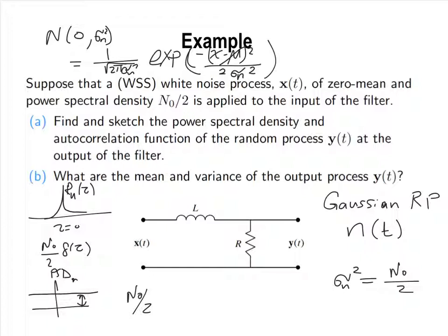Okay? So that at any point in time when you are trying to solve a problem or design a system and you are told that the noise variance is this value, you don't come and tell me, oh, I don't know what's the power spectral density of the noise. You already know it. Or vice versa. You are told you have a noise which is additive white Gaussian and it has a power spectral density of a value n0 over 2 given to you, for example, in milliwatts per hertz or whatever. And then you come and ask me, so what's the variance of this noise so I can model it? You already know it. Power spectral density value is equal to the variance of the noise.